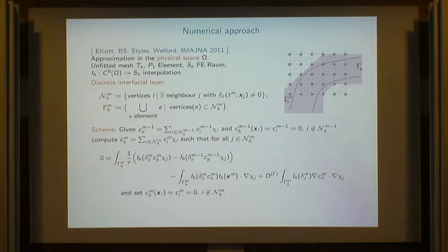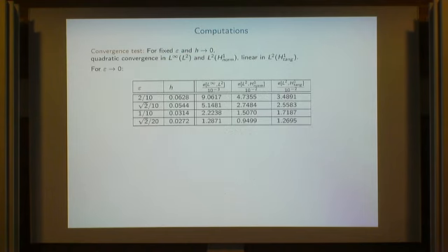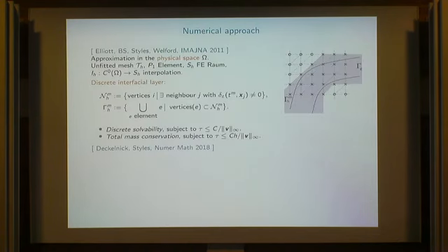For this purpose, we have to make sure that if you advance from one time step to the next, the boundary of this interface does not cross a whole triangle, a whole element. Because then we would lose some information from some points that were associated with some mass here. But roughly speaking, if the time step satisfies such a constraint, then this is guaranteed. You preserve the total mass.